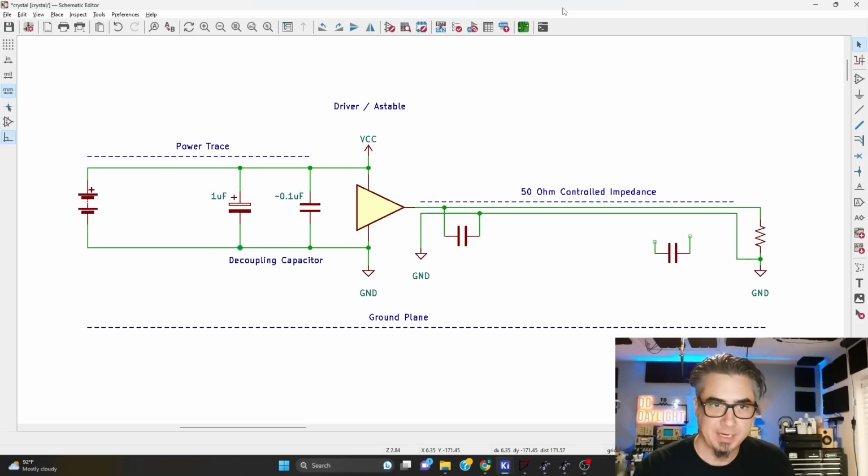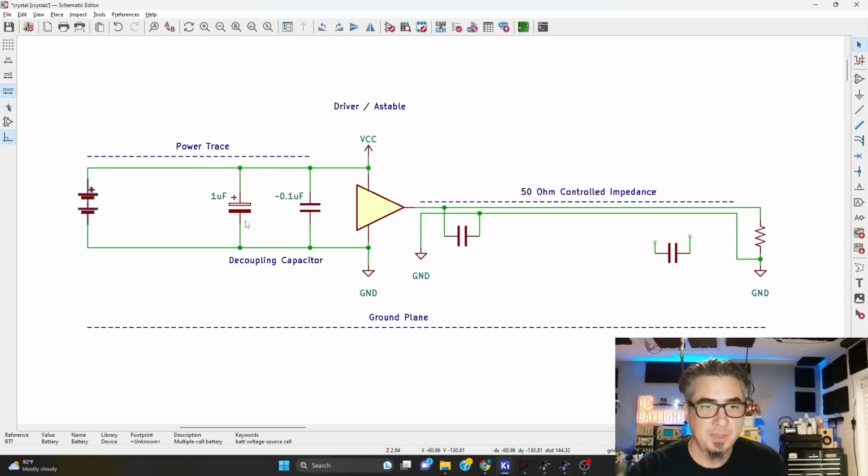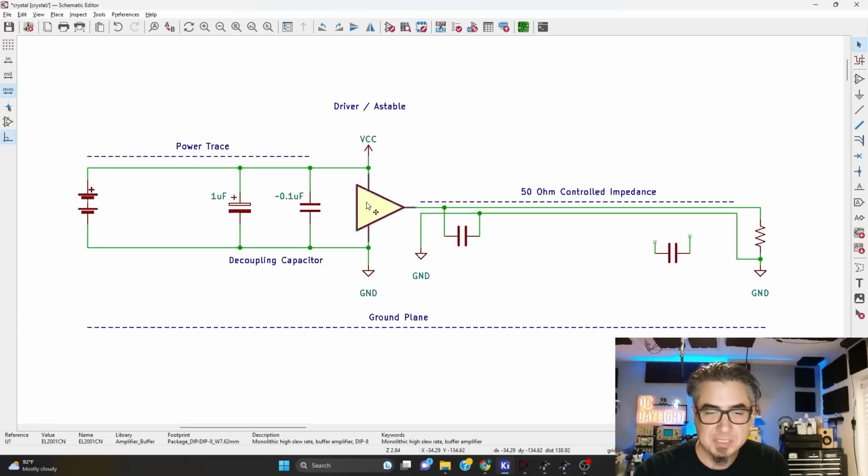So here's a circuit that I was just going to play around with and show how things work. Typically in any circuit you have a power supply and some digital device or analog op-amp or something that performs some function. There could be noise and ripple on the power supply. There are a lot of other circuits connected to that same power supply typically, and these fast transient signals can introduce harmonics and noise on the line, as well as the power supply itself could inject noise into the system.